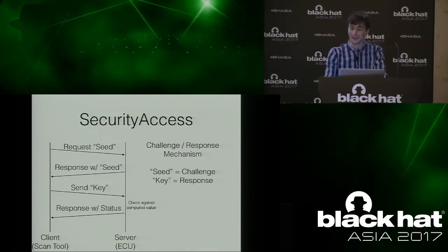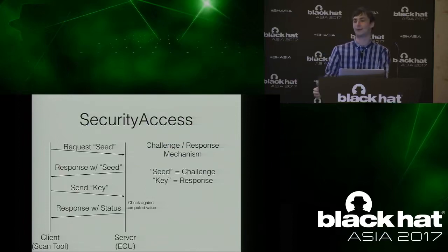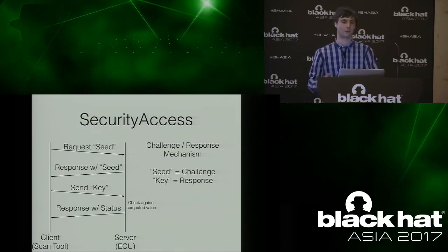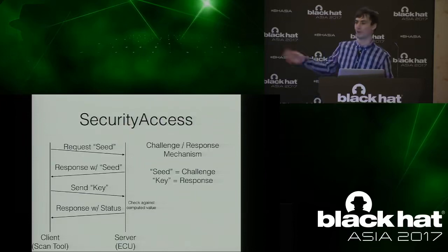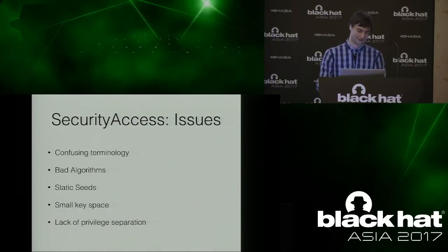Once it's unlocked, it stays unlocked typically until you reset it. So you can use a tool that can unlock this and then unplug it halfway through it doing its thing, and the ECU stays unlocked. Also, there's no integrity to anything you're sending back and forth during this session. They may have implemented that somewhere along the line. Maybe the firmware is signed and their bootloader checks a signature, but the actual protocol doesn't implement anything like that. So, once it's unlocked, you're in. So there's a few issues with this.